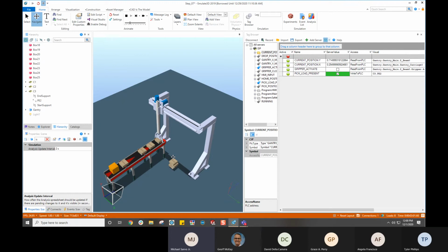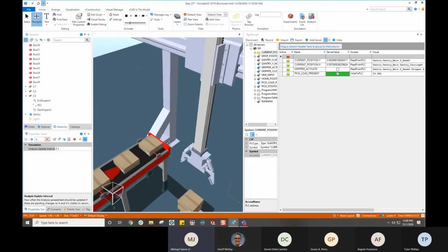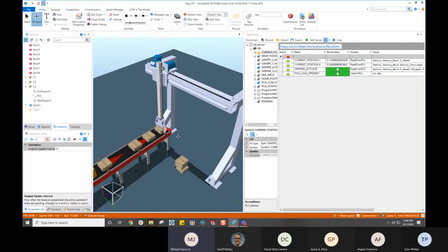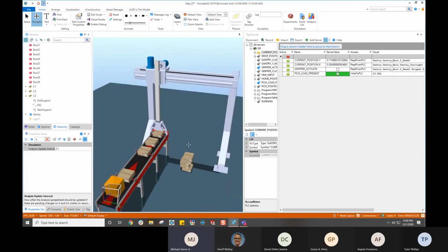They might make the model bend to the will so that their control logic just works. Instead they say, the emulation model is the model, and if your control logic isn't running it right, then your control logic needs to be fixed. And so the controls engineer isn't allowed to tweak the way the model works. They might get to change the positions of the photo eyes and things like that, but they lock them out of certain fundamental changes, and that's just to keep the fidelity clear and clean.